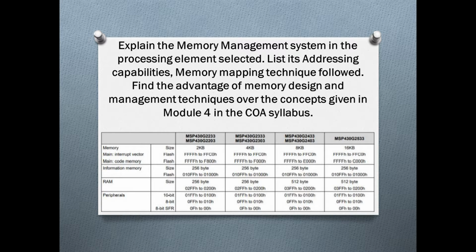Devices with a memory configuration of 64 KB or less use the small memory model with a basic address range of the lowest 64 KB, and do not care about code segments and data pages. The data bus is 16-bit or 8-bit wide. For those modules that can be accessed by word data, the width is always 16 bits, and for the other modules it is 8 bits. They should only be accessed with byte instructions.